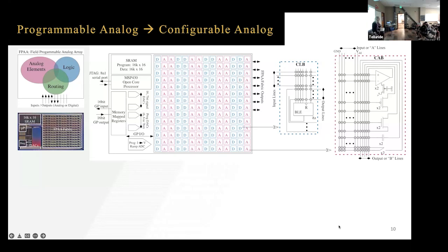This is a 16-bit hardcore. The reasoning for that: one is that there are places where I need it. I need it for cleanup. I'll use it for the programming. It's just useful for interfacing to the rest of the world through all the other IO ports. The chip itself does all of the floating gate programming. Yay. So nothing else would be needed for any of that part of the computation. So there's a lot of pieces in here, including some signal DACs, some other memory-mapped registers, and so on. And SRAM in here, which I always find funny when I look at the chip.